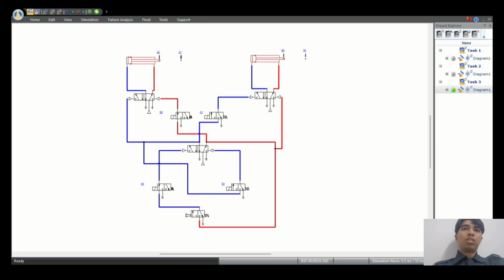211062660. So today I will explain the development and simulation of a pneumatic sequence control system for clamping and riveting operations using Automation Studio. In the setup, we use two pneumatic cylinders. The clamping cylinder A advances first to clamp the sheet metal components securely. Next, the riveting cylinder B advances while the parts are clamped to perform the riveting operation. After riveting, cylinder B retracts, followed by the retraction of cylinder A, completing the sequence.